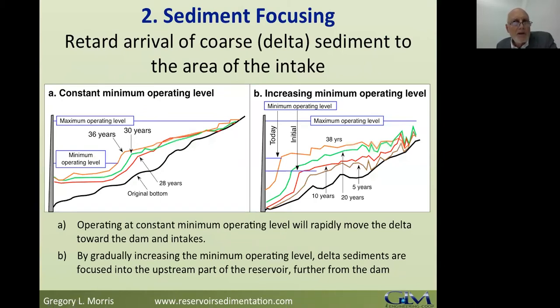Sediment focusing. What you're typically trying to do when you focus sediment is to focus it upstream. Why? Because the delta contains coarse sediment, and when the coarse sediment reaches your intake and gets into your power turbines or your irrigation intake or whatever other element you have, it's typically going to create lots of problems.